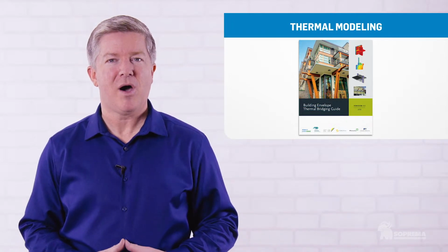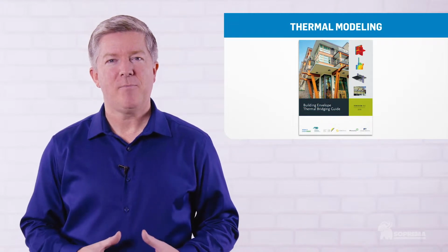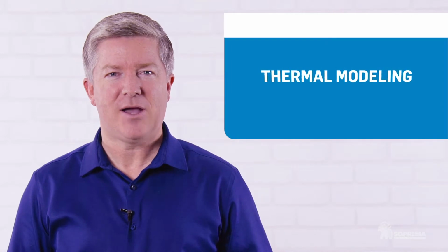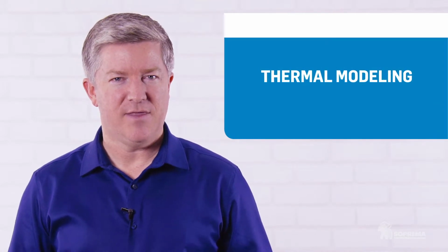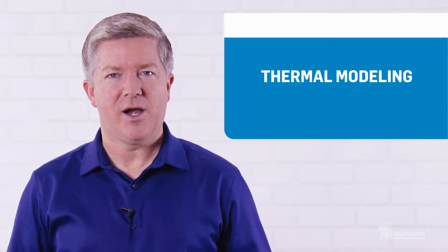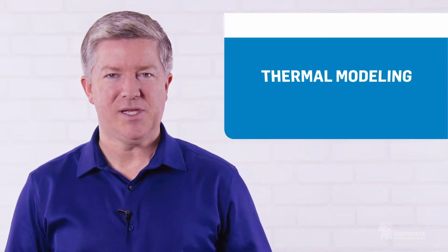They performed model calculations for us, and part of these results will now be presented. Thermal modeling of exterior wall assemblies was performed under various conditions in order to evaluate the impact of the amount of exterior insulation, the amount of cavity insulation, and the level of thermal bridging on effective R value of the assemblies. Results were then compared to NECB requirements.